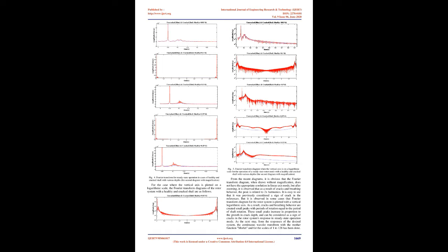In the above relationships, Kc is the stiffness matrix of the cracked element, Kuc is the stiffness matrix of the healthy element, and K is the assembled stiffness matrix of all the elements in the case when the crack is fully open. C. Modeling of the breathing behavior of the crack in the rotor system. Breathing cracks, in both fixed and rotary shaft coordinates, have variable stiffness, and during a full shaft rotation cycle, different modes can be assumed for the contact position of the crack edges with each other.